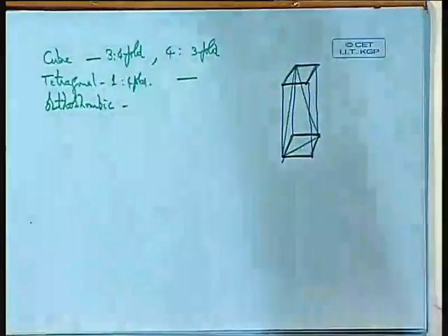And when we come to the orthorhombic, the highest symmetry that it has is a twofold symmetry. It has nothing beyond that. It does not have a threefold symmetry, because you imagine a 1-1-1 plane in an orthorhombic. You see, a 1-1-1 plane can be thought of in any crystal system, okay. Why only in cubic? We can think of 1-1-1 even in a triclinic, okay. 1-1-1 is just a plane, okay. Joining the three corners you get a 1-1-1 plane. But the only interesting thing in a cubic is that the 1-1-1 plane is an equilateral triangle, which gives it a threefold symmetry, and that is characteristic of a cube. Only a cube has that, okay.